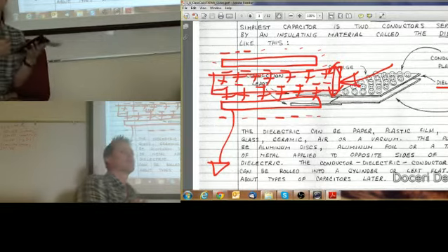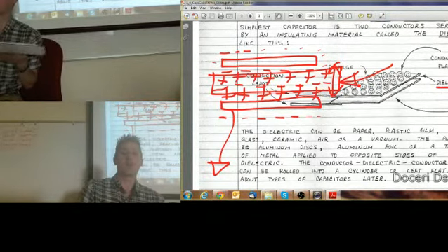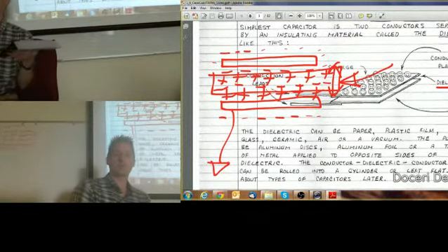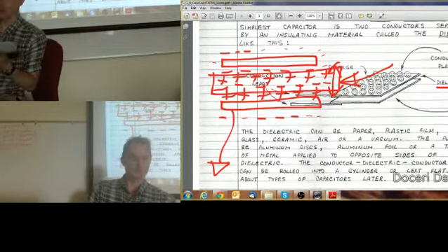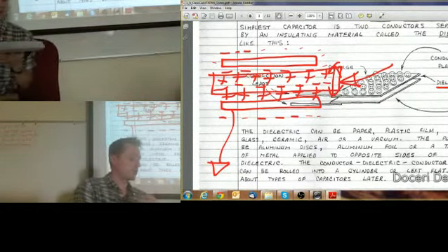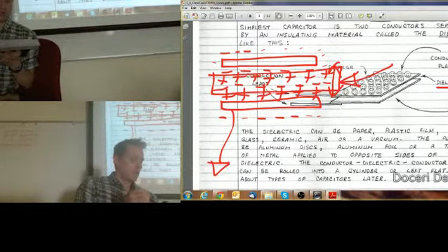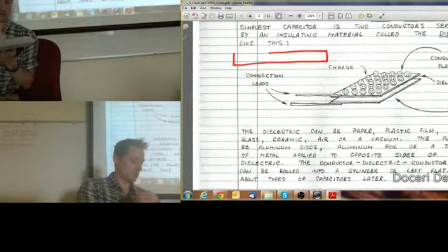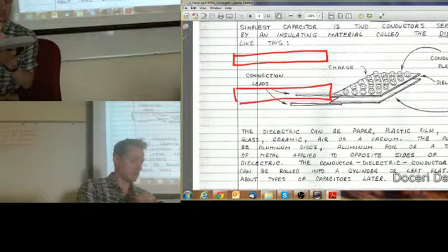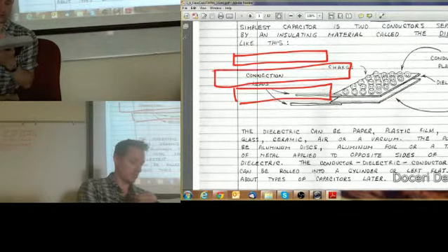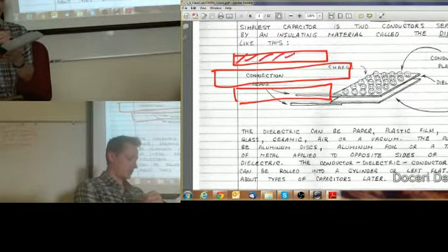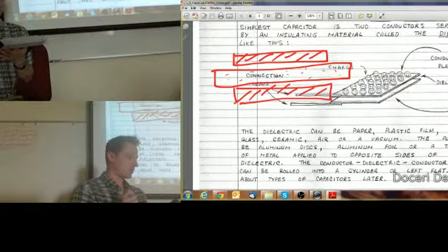One of the best performing dielectrics actually is ceramic. Ceramic capacitors have what we call the lowest equivalent series resistance. Now, some of the dielectrics you put inside here actually do conduct. Let me erase these, it's too busy over here. Normally these two plates, the top plate and the bottom plate, don't touch each other. Let's just say that this is metal, and this is some type of ceramic or something.